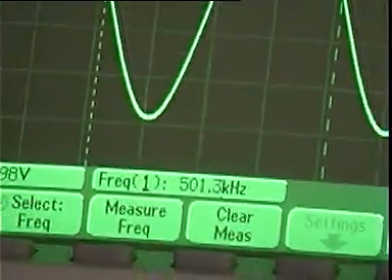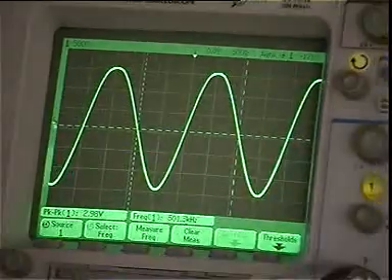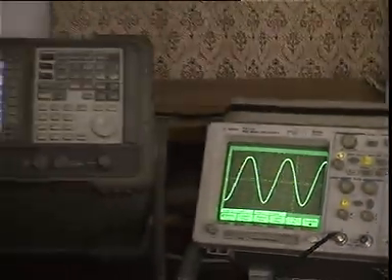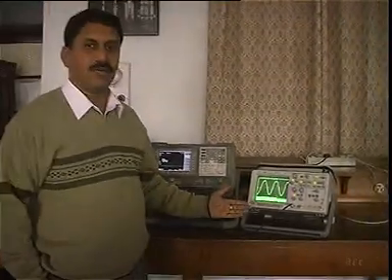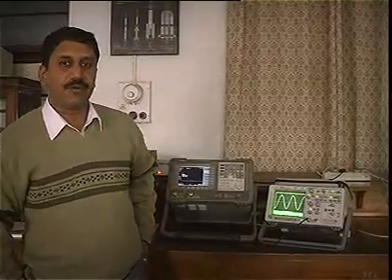When you don't connect any input to the voltage control oscillator, the voltage control oscillator will oscillate at its natural frequency, which is called as the free running frequency, and that free running frequency is 500 kilohertz. That is the frequency of the carrier we have chosen. Now FM, unlike amplitude modulation, is little more involved. The analysis of FM is quite difficult compared to the amplitude modulation. But for demonstration purpose, it becomes simplified if we choose the message signal to be a simple sinusoidal signal.